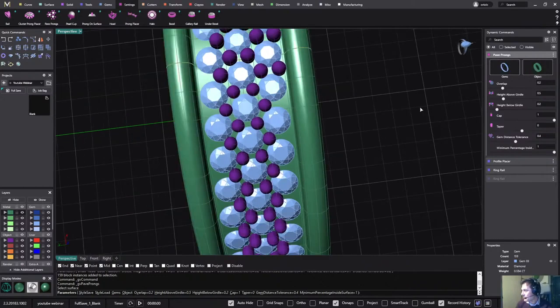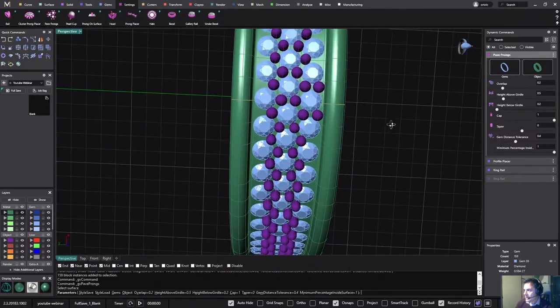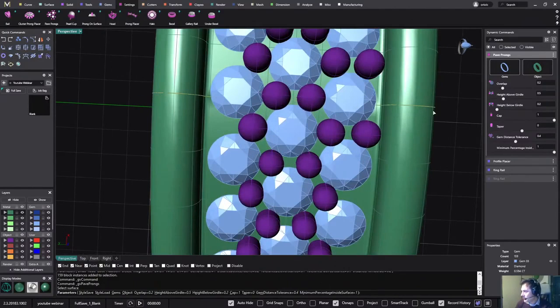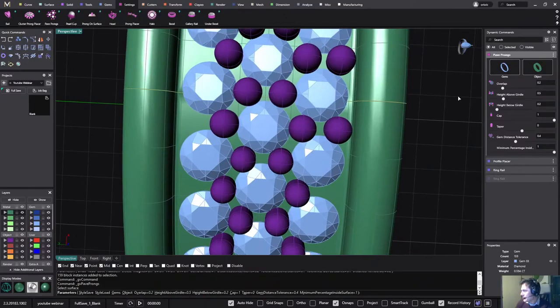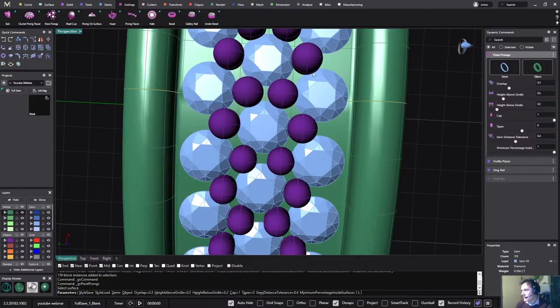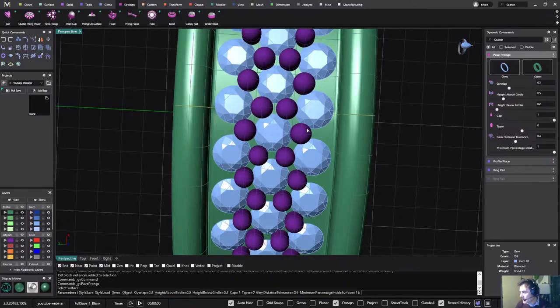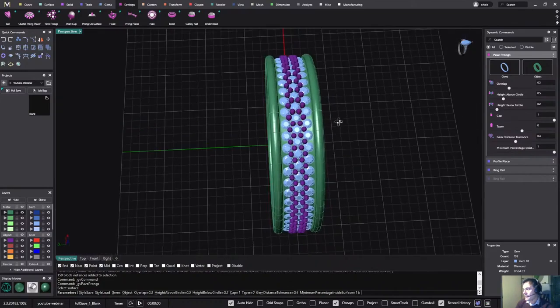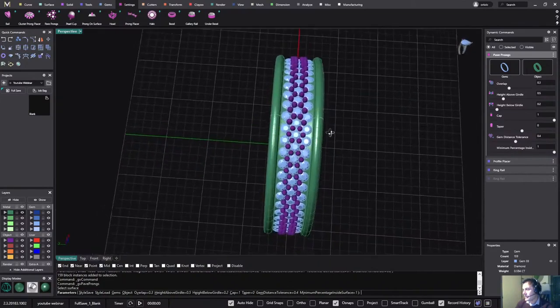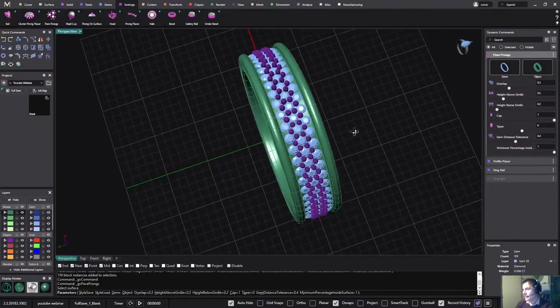So we have the tool here, and as you can see, just to show you how it works, if I go now and I say overlap is 0.2, if I go to 0.3, what it will do is grow the prongs, and now you see the prongs are a bit bigger and are more inside the stone. All right. So now we have everywhere the same.